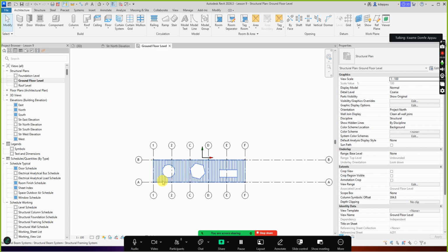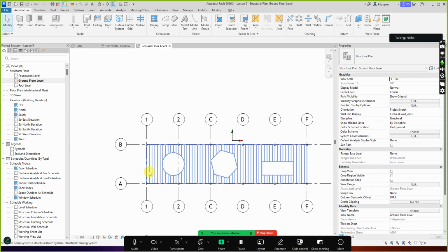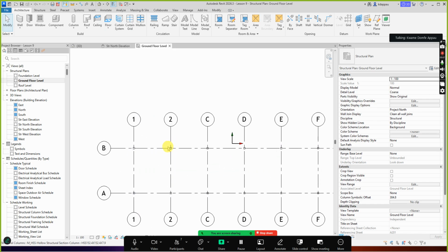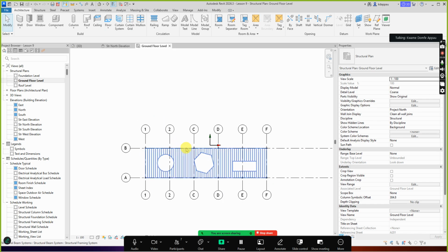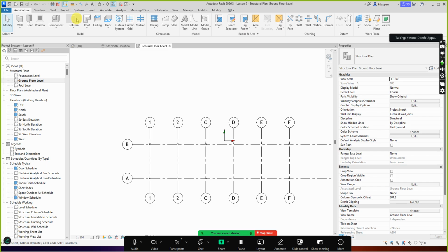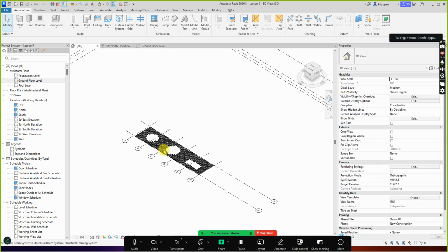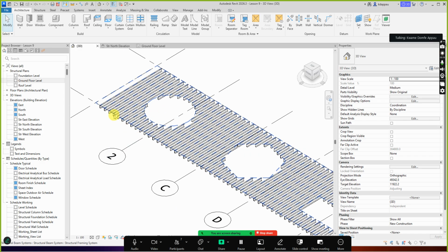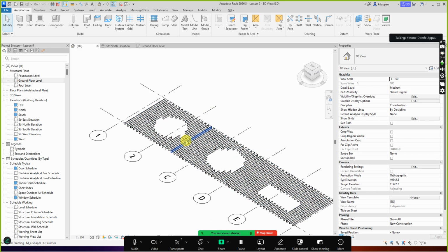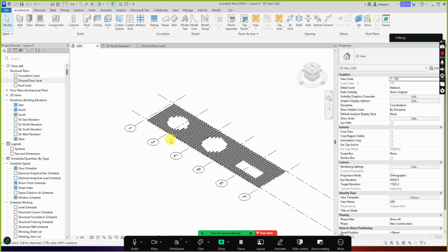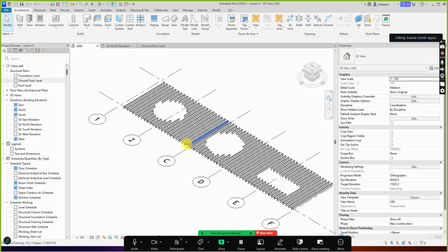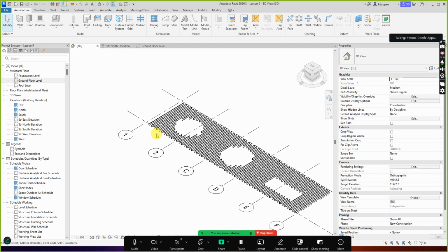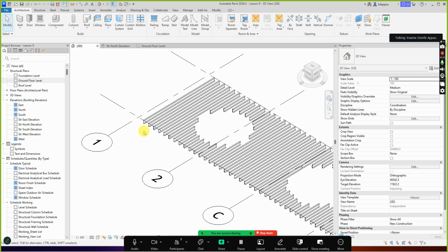Most of the Revit structural elements will be constrained to the grid, so that when a grid moves, the structural element will move with the grid. Yesterday, we looked at some few things. We looked at columns, we looked at beams, we looked at beam system. Those are the three elements we looked at for structures. There are structural walls. We've already discussed walls. That is why I did not bring it up.